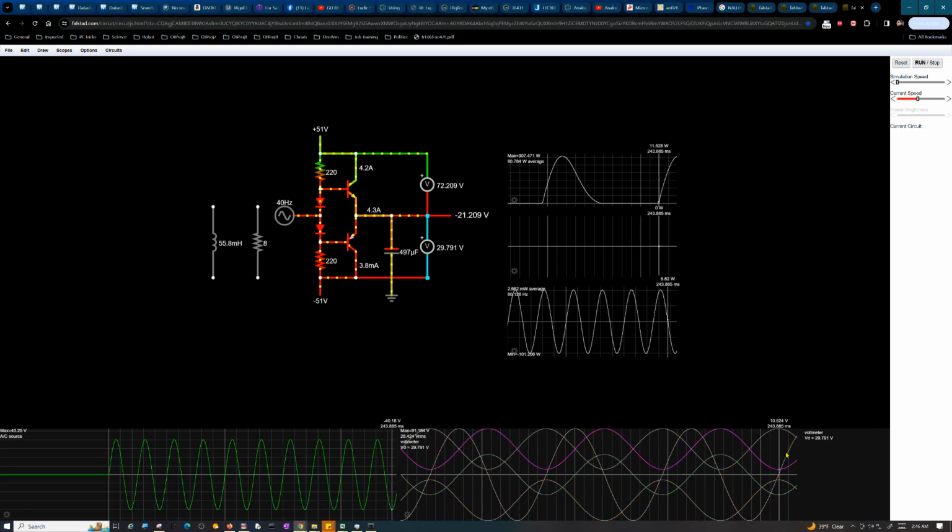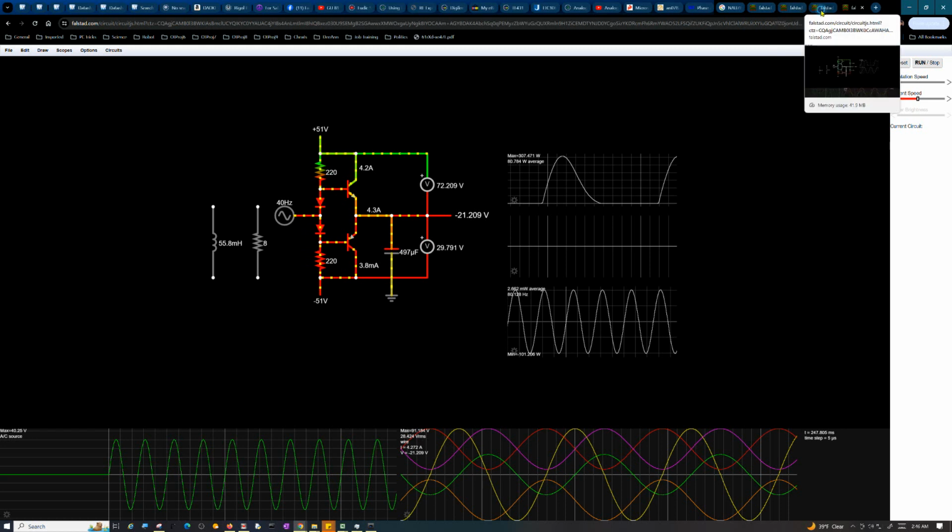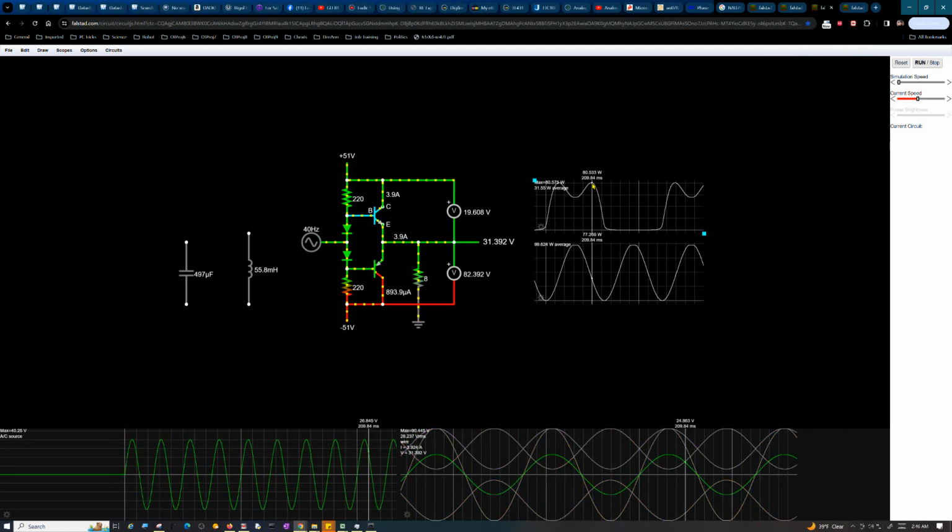But at any rate, this gives you a clue if you want to understand impedance loading. And this also shows you why. Look at that, 307 peak watts versus our resistor version, which was 80 peak watts. It's broader, but it's still way less overall dissipation, but you've got actual full dissipation in your load, so that's about the best you can get. These two powers are probably approximately equal, via the maximum power transfer theorem, I assume.